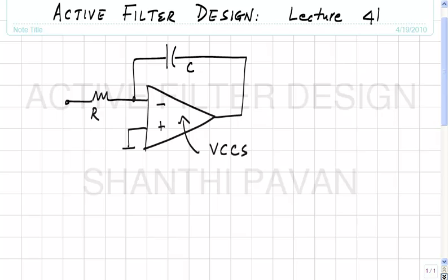Then we said instead of putting GMs in parallel, which is what one means when one says a large GM, the other alternative was to increase the transconductance by cascading transconductors, and in principle at least it seems as if cascading transconductors should give you ideally infinite GM at low frequency, and beyond, as frequency increases, unfortunately the parasitic capacitance at the output of the first transconductor introduces poles.